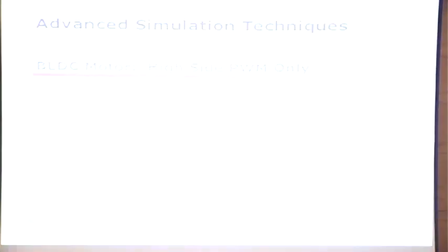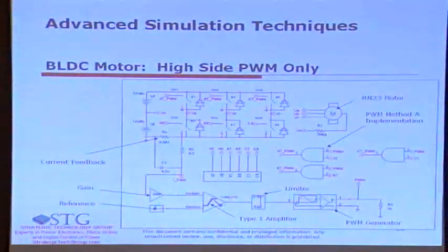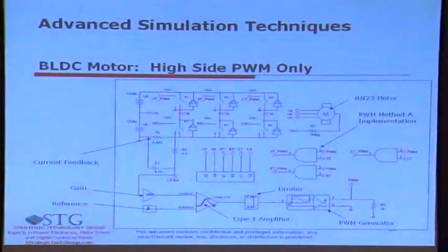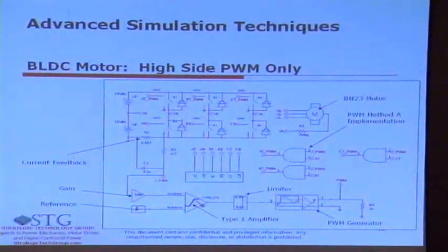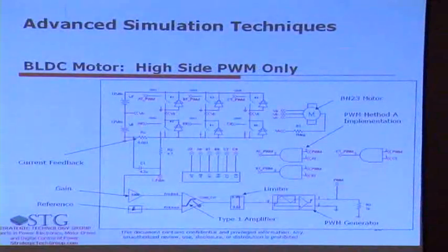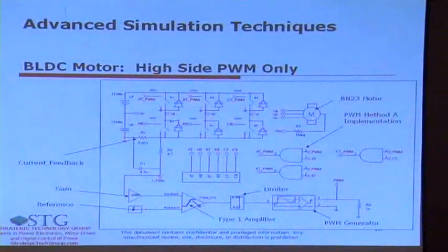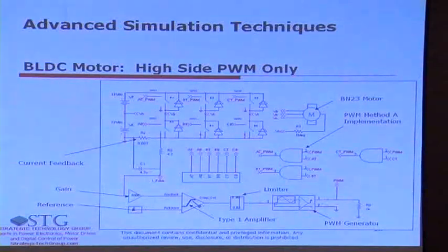Why are we using another equation to generate the PWM signal? We have a triangular signal, and this reference section and feedback section will give me this duty cycle setting. So the comparison of the duty cycle setting with the triangular will give you the PWM signal, right? Yes. And what is the additional PWM signal we are using with the equations?